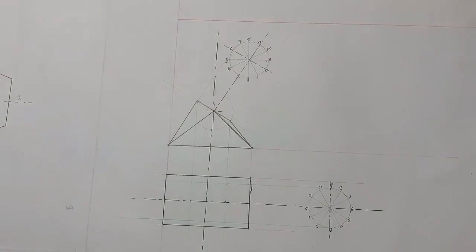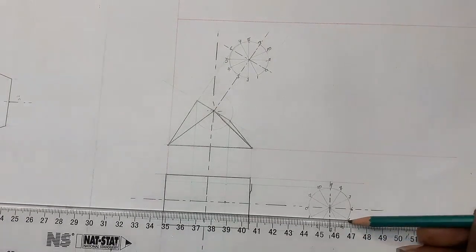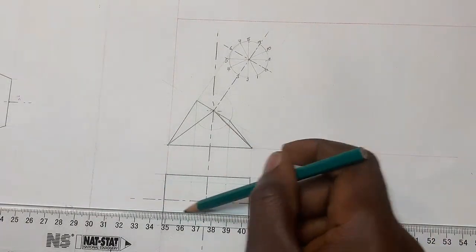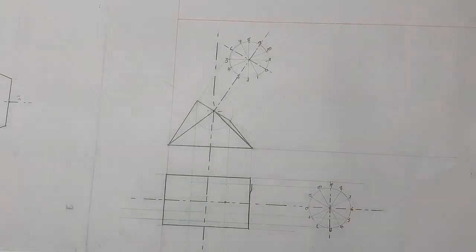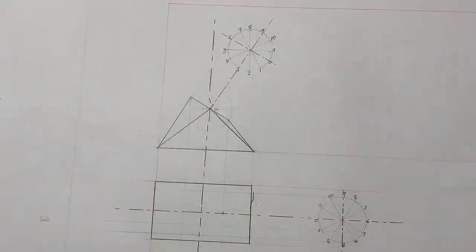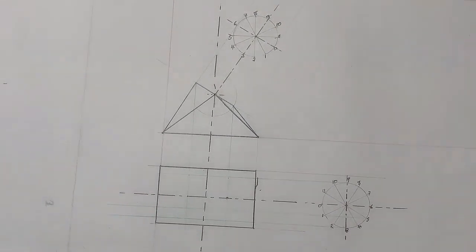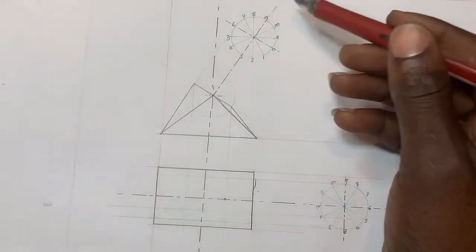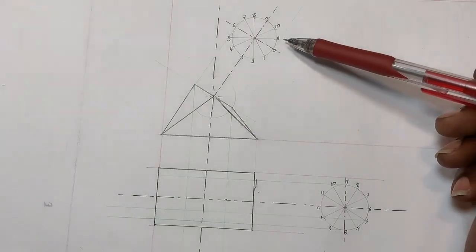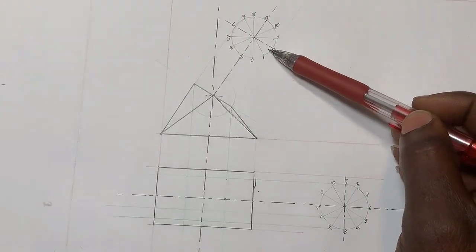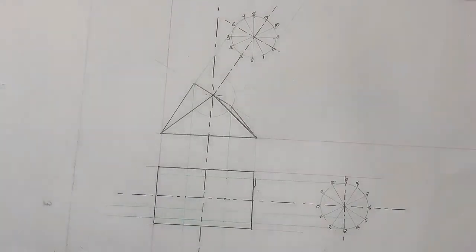So point 1. If I project point 1, I'm going to learn that point 1 is in the same line with 5. There it goes, faint. There it goes, faint, and it's in the same line with 5. We draw it faint, just like this. And then go to your what now? To your auxiliary. Then it's going to be 1. This side is going to be 1 in the same line with what? With 11. 1 in the same line with 11.